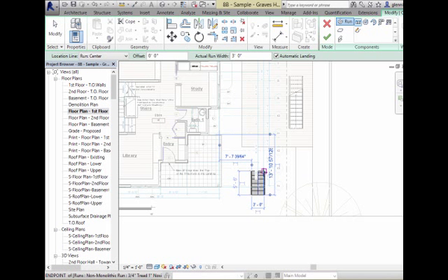Now as I come on back, watch out for this. The temptation is to come over here and click right on the end point of this and pull back. What you don't want to do that for is you're actually indicating the center line of the stair, and I'm actually creating two halves of a stair. It's very similar to that picture I showed you at the beginning of the quarter. So that's probably not a good thing in terms of having a double back that way. You've got to leave yourself a little bit of breathing room between the stair sections.